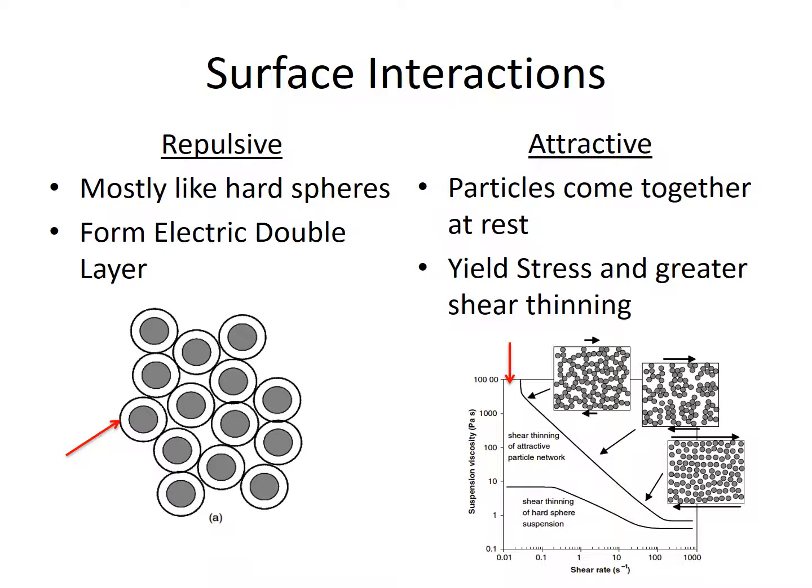Continuing from that, we see drastic shear thinning as shear rate increases, because the large chunks of particle network that entrain lots of fluid inside them are being broken into smaller and smaller chunks, freeing up fluid and easing the flow. So that covers the basics of colloidal rheology. I hope you learned something and are ready to dive into more complicated colloidal systems.